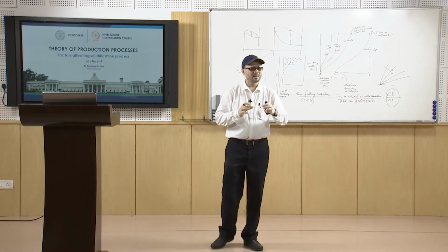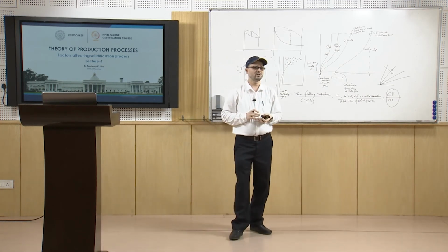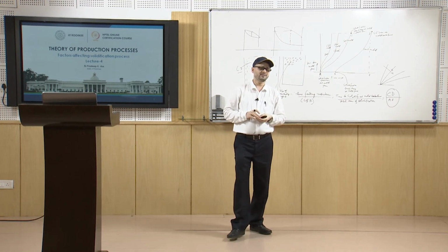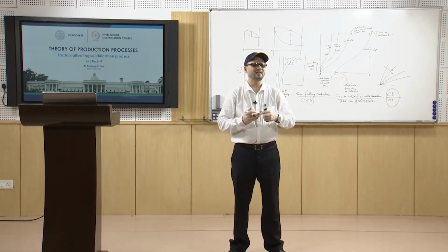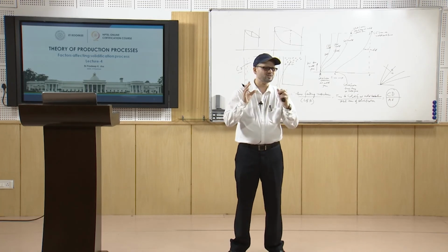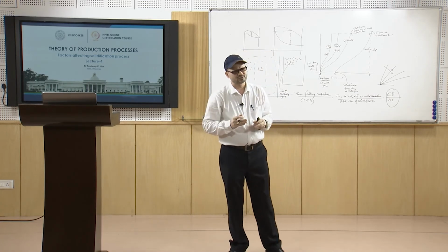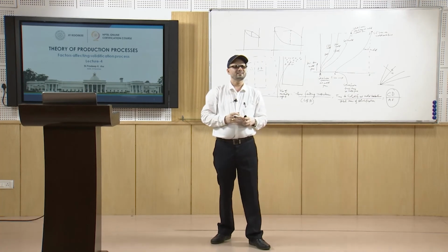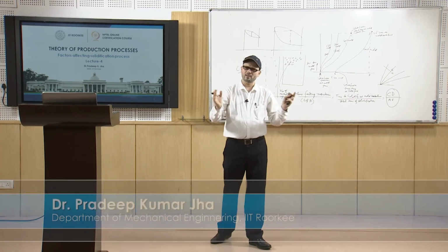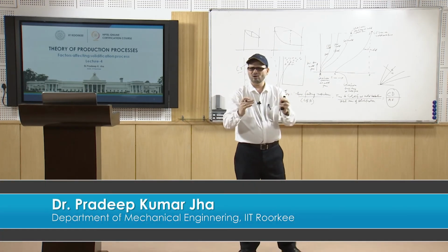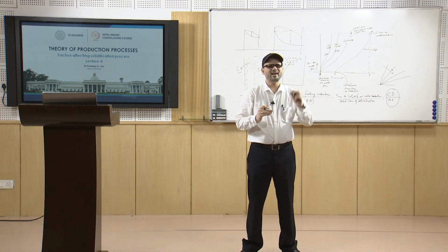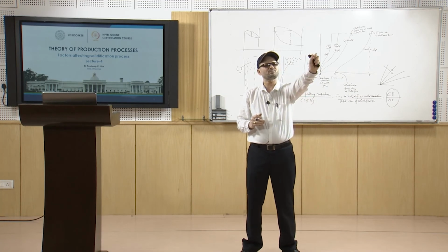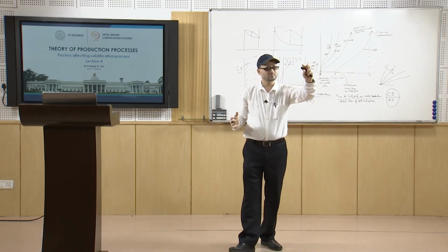These are the main things which control the solidification process, and solidification is very important, because ultimately the quality of the cast depends upon how the solidification proceeds. We will study later how the solidification proceeds from the sides, and also how the solidification finishes, where should be the last point where the solidification should finish.